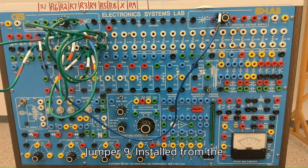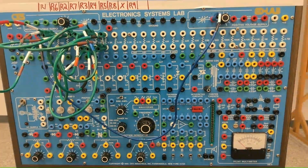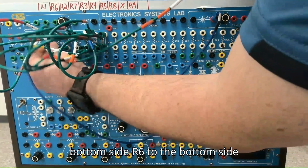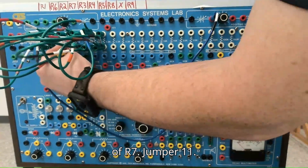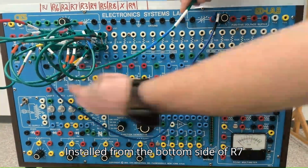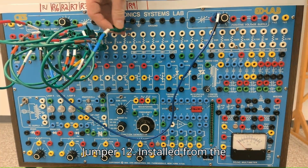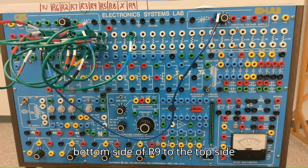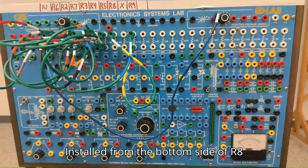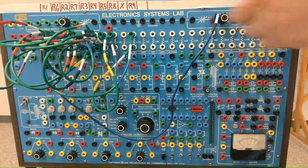Jumper 9. Installed from the top side of R6 to the top side of R7. Jumper 10. Installed from the bottom side of R6 to the bottom side of R7. Jumper 11. Installed from the bottom side of R7 to the top side of R9. Jumper 12. Installed from the bottom side of R9 to the top side of R8. Jumper 13. Installed from the bottom side of R8 to the negative voltage supply.